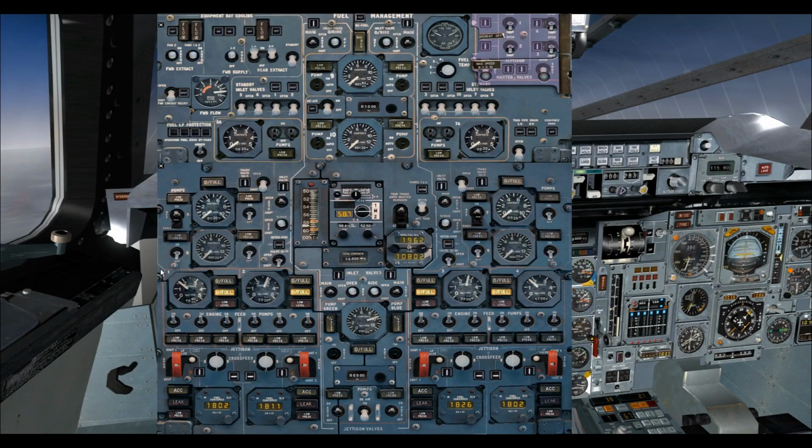Just a note of caution for consistency with regard to the video. In this section of the video, I actually flipped the switch from aft trim to normal when tanks 6 and 8 were at 2,500 kilos. Previously I did it at 4,000 kilos, so you'll notice a few different numbers in tanks 1 and 4, and also the center of gravity.